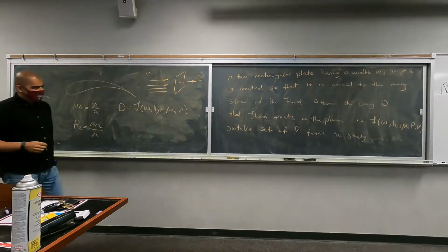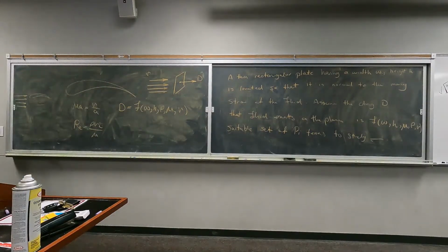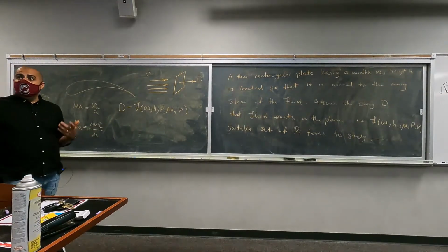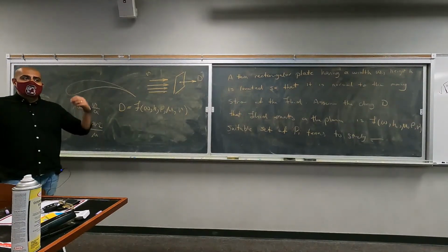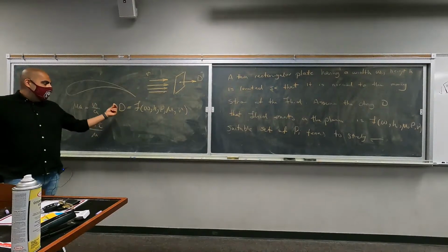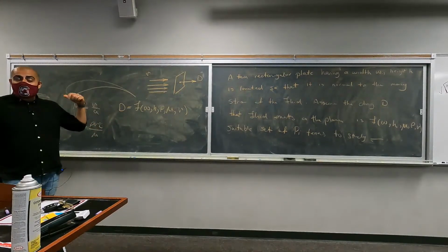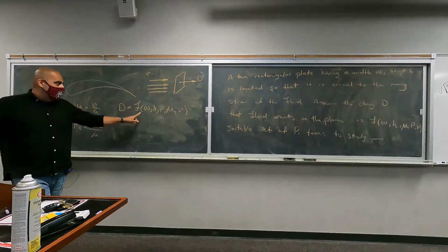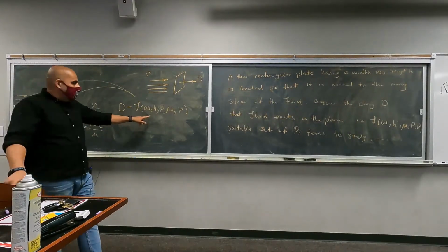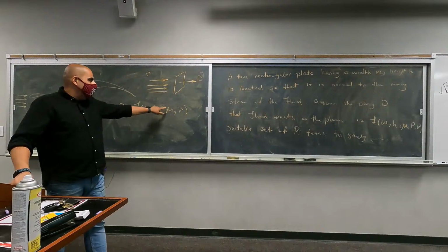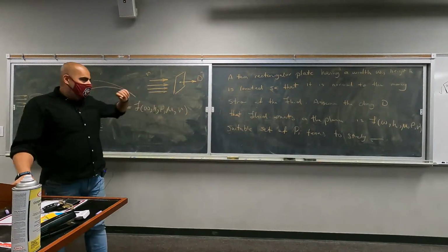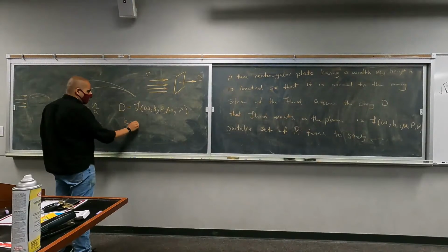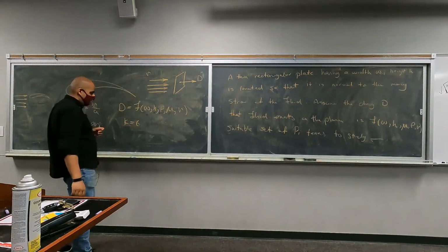Okay, velocity. So let's say we want to start the Buckingham pi theorem analysis. What should we do? The first step is to count the number of variables you have. One variable is the drag force itself. Another one is the width. The other ones are height, density, viscosity, and velocity. So how many variables is that? 6. So your K is equal to 6.